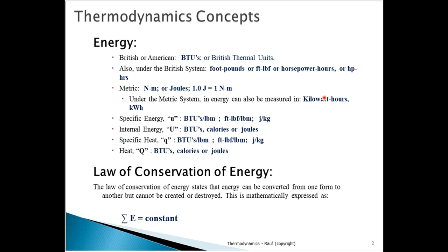the power in the electrical component would be expressed in watts, where 1 watt is 1 joule per second. And you multiply joule per second by time, you end up with joules, which is a unit for energy. So therefore, kilowatt hours is a unit for energy.